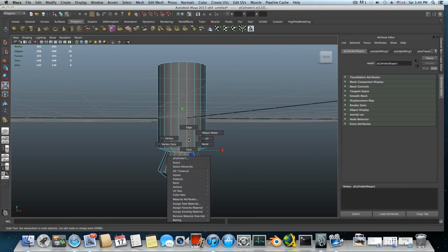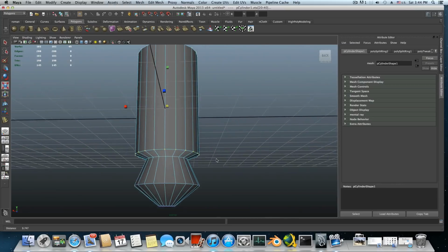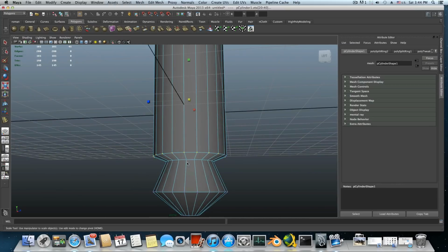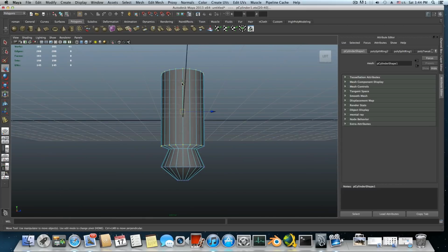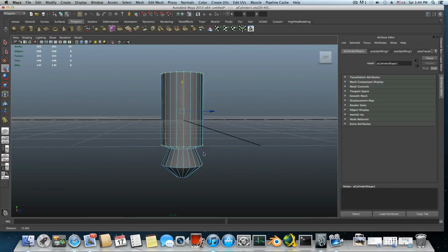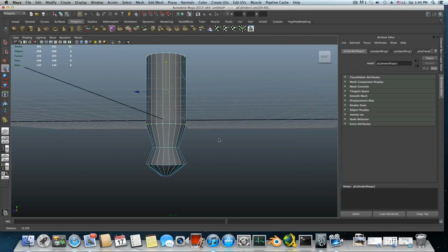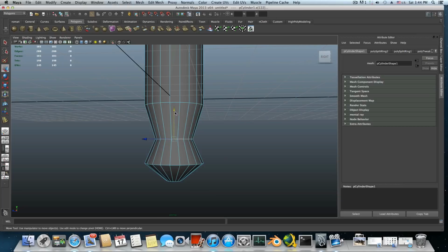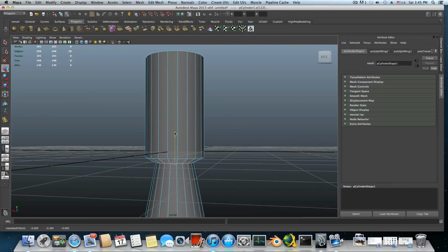So what we should do is right click on this object, choose all the vertices like here, but don't grab those here, it's not necessary. This row I want to stay where it is, and also the upper ones, and then just pull it with your move tool. Okay, not like that. We need to make sure we do it correctly, so let me do it one more time like that, then pull it up just a bit higher, and again grab this edge and move it like so. Okay, so that will be it. And from here what you should do is tap F8 to bring it back to object mode.